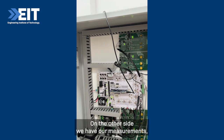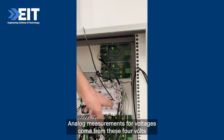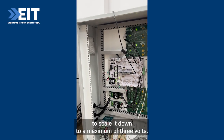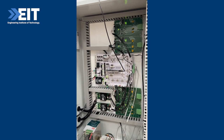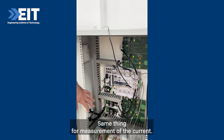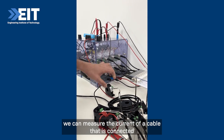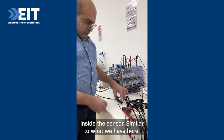On the other side, we have some analog and digital measurements. Analog measurements for voltages come from these four boards, which scale the voltage down from up to 1000 volts to a maximum of 3 volts, and that makes it readable by the microprocessor. Same thing for measurement of the current. We have two boards here, and they use Hall effect sensors with which we can measure the current of a cable that is connected inside the sensor, similar to what we have here.